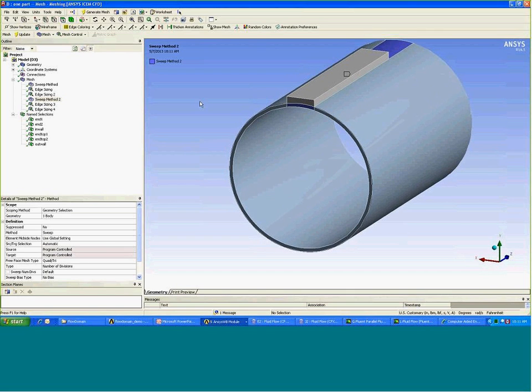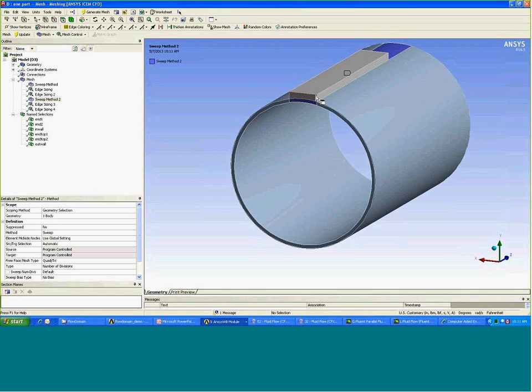Because these three flow volumes belong to the same multi-body part, the top rectangular section would be meshed based on whatever mesh is generated from here, and Workbench would generate a flow-through mesh across the interspaces between these volumes.